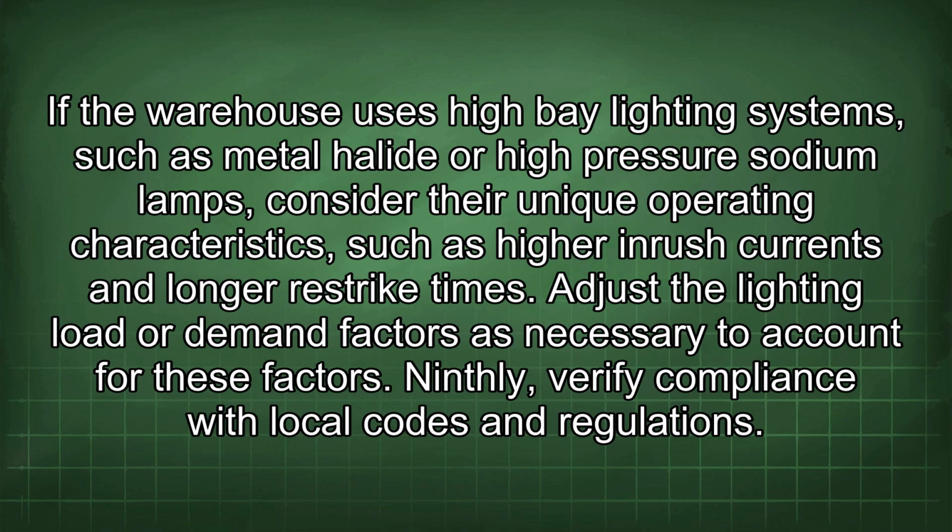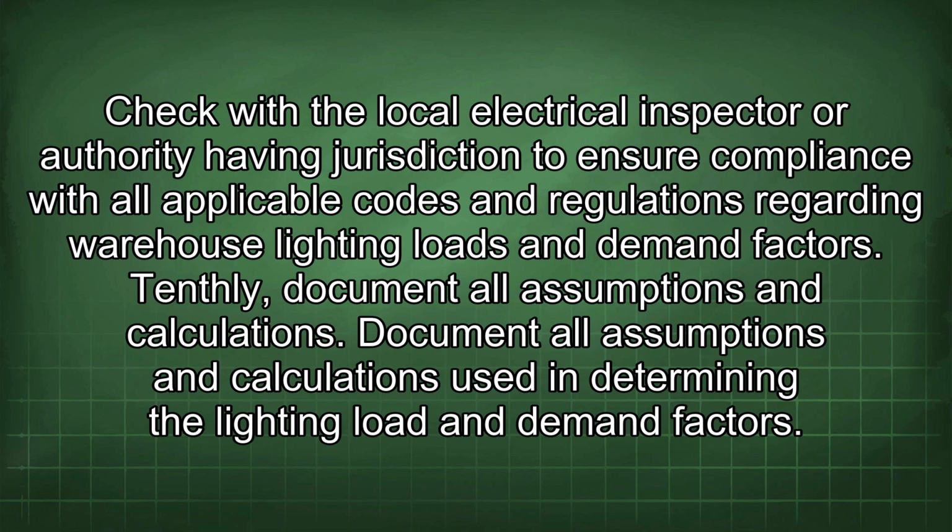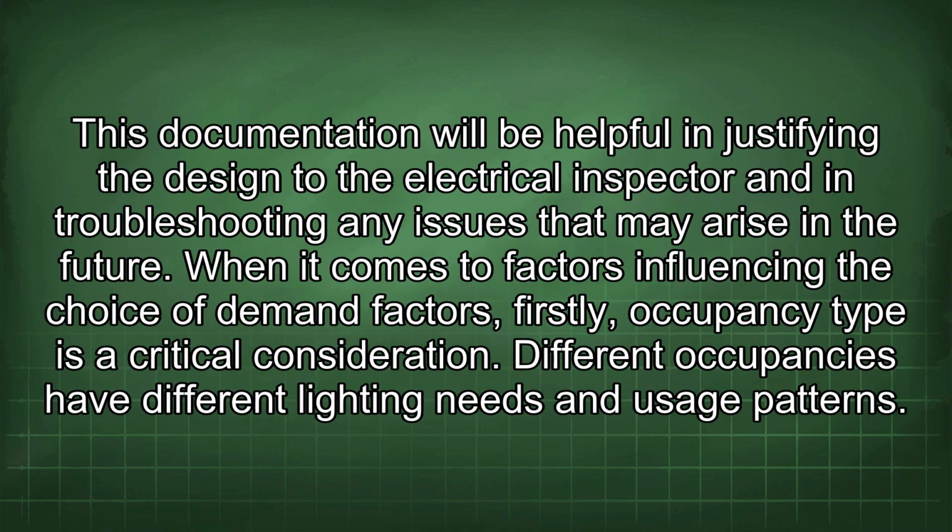Ninthly, verify compliance with local codes and regulations. Check with a local electrical inspector or authority having jurisdiction to ensure compliance with all applicable codes and regulations regarding warehouse lighting loads and demand factors. Tenthly, document all assumptions and calculations used in determining the lighting load and demand factors. This documentation will be helpful in justifying the design to the electrical inspector and in troubleshooting any issues that may arise in the future.